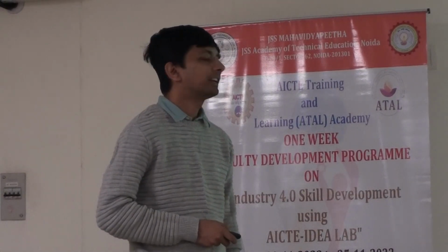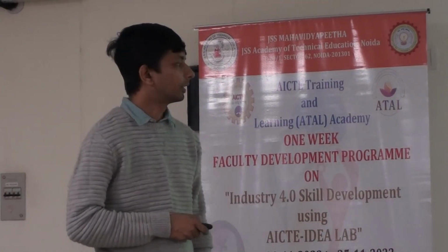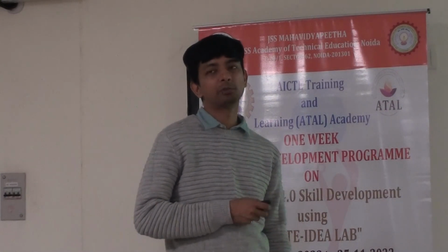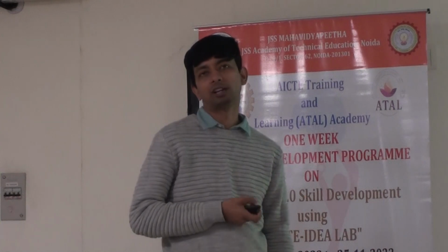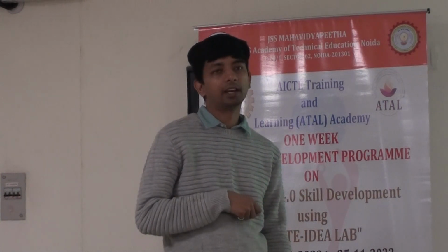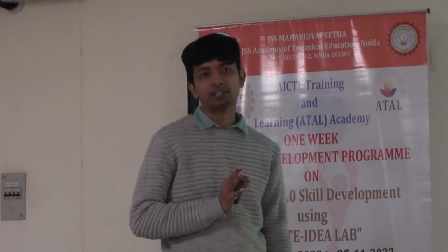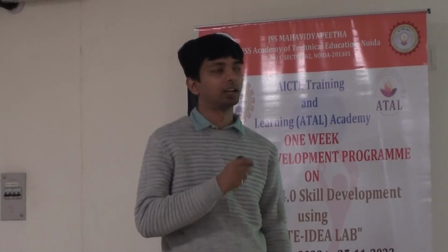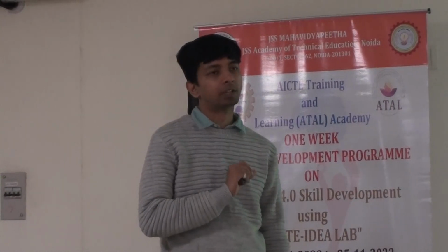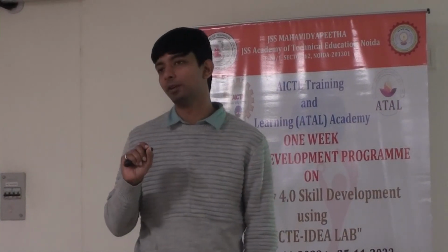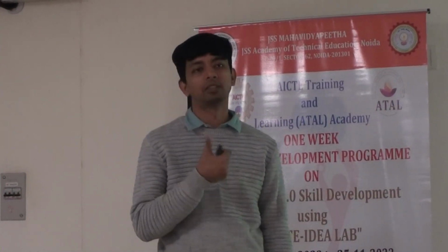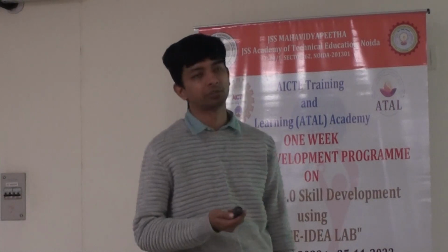Cutting of highly reflective materials, again, depends on the wavelength. For example, if I am using a fiber laser and I want to cut, say, pure copper, then it may not be a good idea, because copper has a very low absorptivity in the 1064 nanometer range. But if I select a 532 nanometer laser, then definitely the same cutting operation can be done with ease. But 1064 may not be suitable.